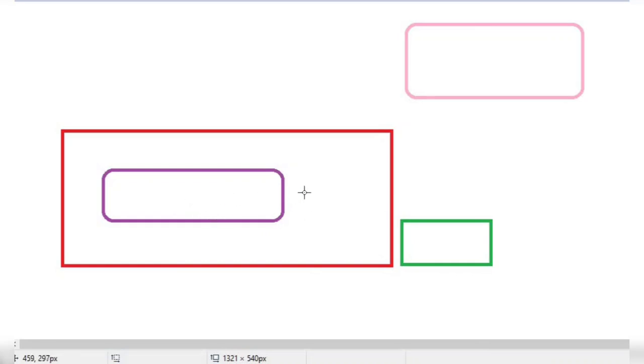So what will happen? The persons who are going to work inside should be trained, so they will show the certifications of an FME worker, and all the stuff belonging to them, like personal items, coins, watches, rings, chains, jewelry, should be kept here on the desk before entering this FME zone.